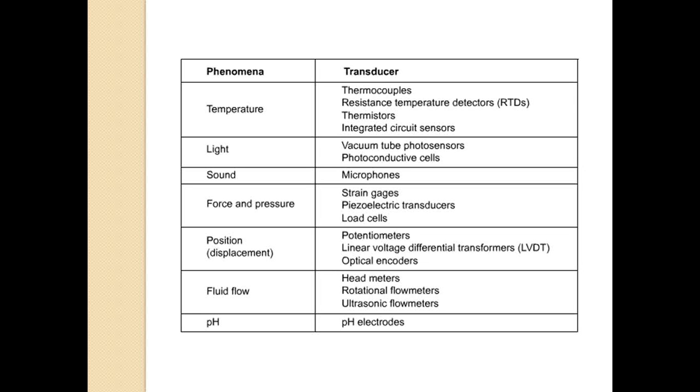It is mainly designed for students to carry out their academic projects. The main things in it are analog in, analog out, and DIO. Analog in is used to acquire signals from the external world. Analog out is used if you want to simulate a signal, say you want to generate a 5 volt pulse of on and off period to control your stepper motor or any motor. That generation can be done from analog out, which means you're generating from your system. Then you have DIO, which is digital in, digital out, which can both acquire and generate.